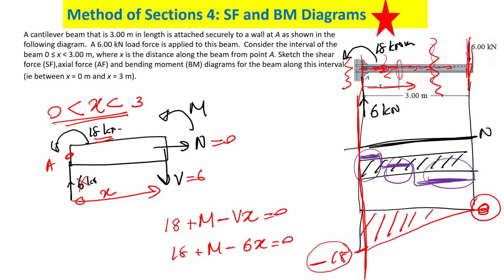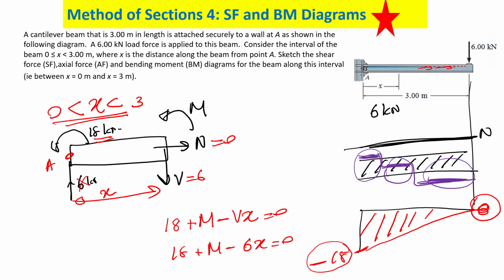And also here you have a negative bending moment. I told you, negative bending moment means, I'll show you here. When you have something like this we call a cantilever beam. This one bends like this, isn't it? Because of this force. It's hogging. I told you, if a beam bends like that, angry face is negative. So you can see negative.